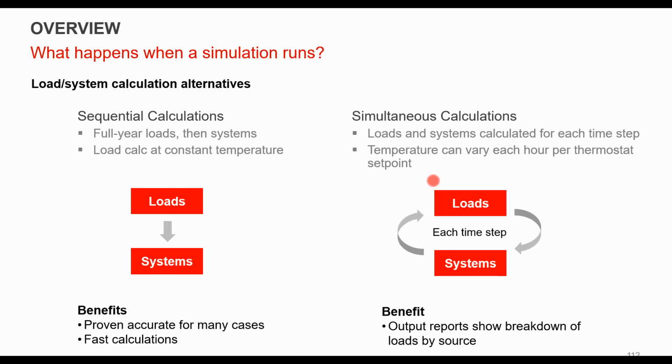So in EnergyPlus, you might have non-convergence because you have this feedback loop. Whereas say in DOE-2, you would just have hundreds or thousands of unmet hours, right? It would just say that consistently you can't meet it. In this case, you might not actually converge. So this, again, is very helpful on the simultaneous side to understand where loads are coming from.